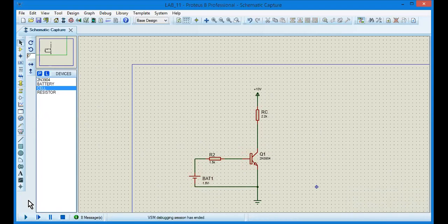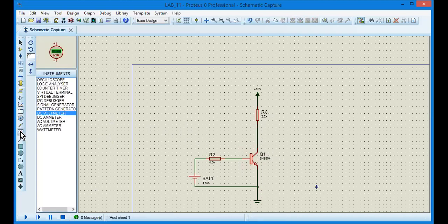So for the first part of the lab, you need to measure the voltage VCE, right? Or V out, which is at VC. So actually we need to measure VC. So we're going to take a DC voltmeter and we're going to put it, and this you've done before. This should be a walk in the park for you, right here. And when we play, we can see the values and we can take them down.